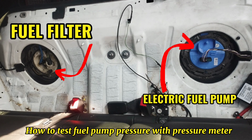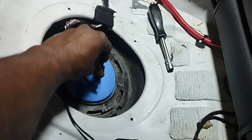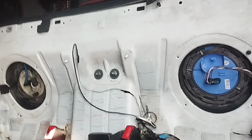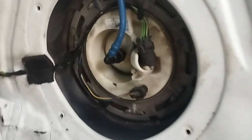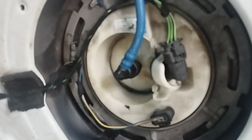How to test fuel pump pressure with a pressure meter. I will plug the fuel pump wire into the socket, then check the fuel pump pressure. From the fuel pump the petrol enters the fuel filter, and from the fuel filter to the high pressure pump in the engine compartment. The petrol from the high pressure pump enters the common rail, and from the common rail the petrol enters the injectors and supplies the engine.